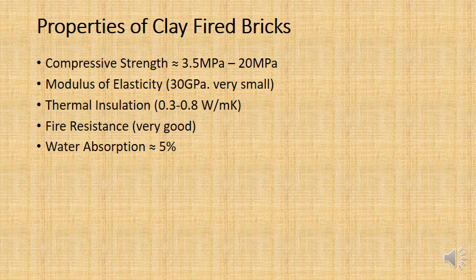So it's all a little bit confusing. It's a bit of an odd unit, but what you need to know is that basically the lower that number, the better the insulation. And so clay-fired bricks are very good insulators. That's quite a low number, 0.3 to 0.5. It's pretty low. And I'll have to say that I have been to a few of the houses that have been made out of clay-fired bricks, and they're a lot more comfortable than the houses that have been made out of concrete blocks.